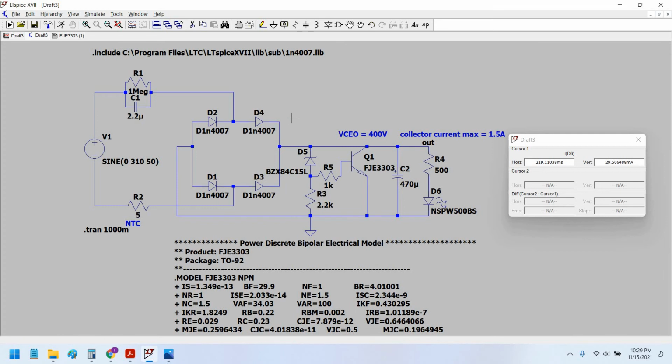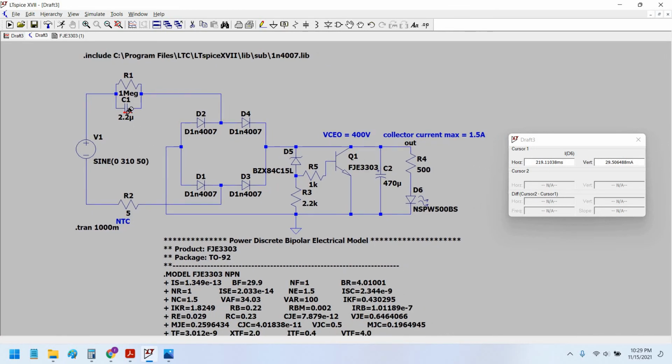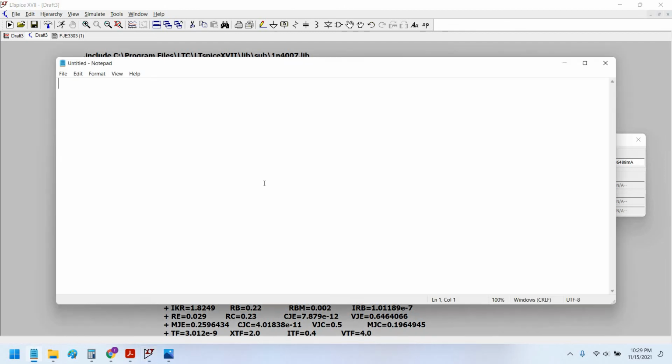So just to elaborate a little bit about this capacitor, which is the load current setting capacitor. This actually works like this. The capacitance has a reactance at AC voltages. So Xc is equal to 1 upon 2 pi Cf, where f is equal to 50 Hertz and C equals 1 microfarad.